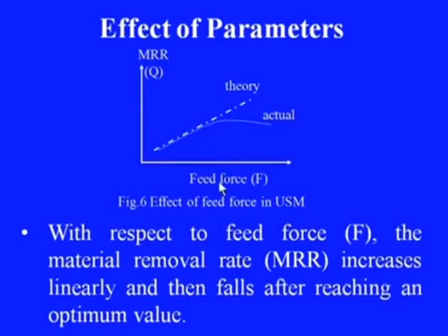Here, as far as the feed force is concerned, this is the characteristic, and this is what theoretically it should look like. That means, as the feed force increases, the material removal rate also should increase linearly at the same rate theoretically.